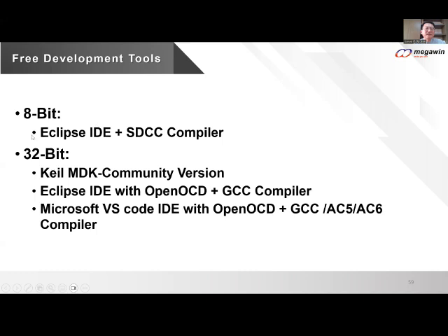But I need to mention this is only for the compiler and the IDE. We don't have a debug function like ICE for this environment. So customers will need to use something like UART printf to output the status to know the internal situation of the code.